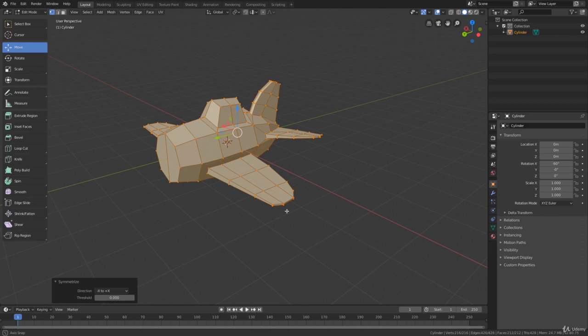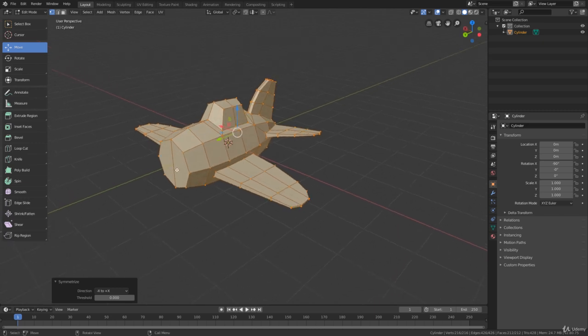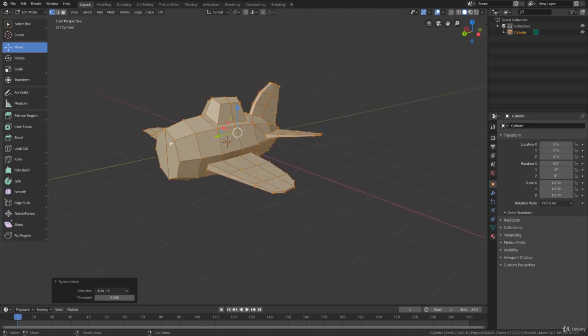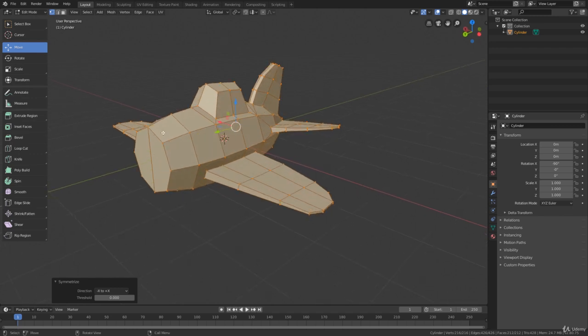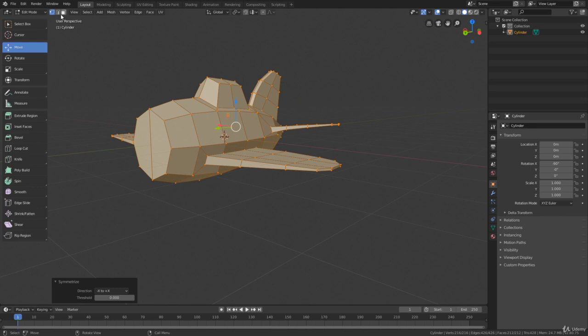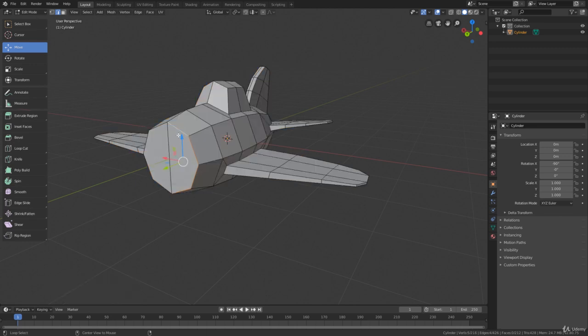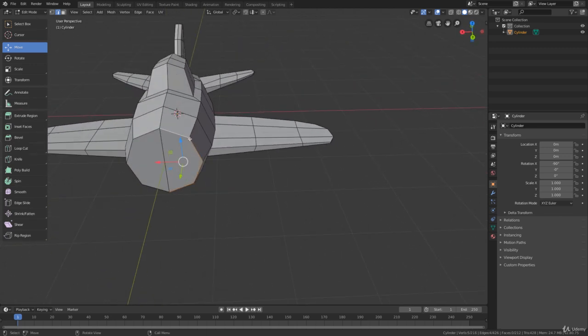And now, to finalize this lesson, I'm going to create a chamfer and a hole here in the front of the airplane, so that we can add in another lesson the helix of the airplane here in the front. Okay? So I will start by creating a chamfer in this front part, and for this I will activate the edge selection mode and select this loop here with the Alt key, and with the Shift key pressed, I will need to click on the other side to select the complete loop.